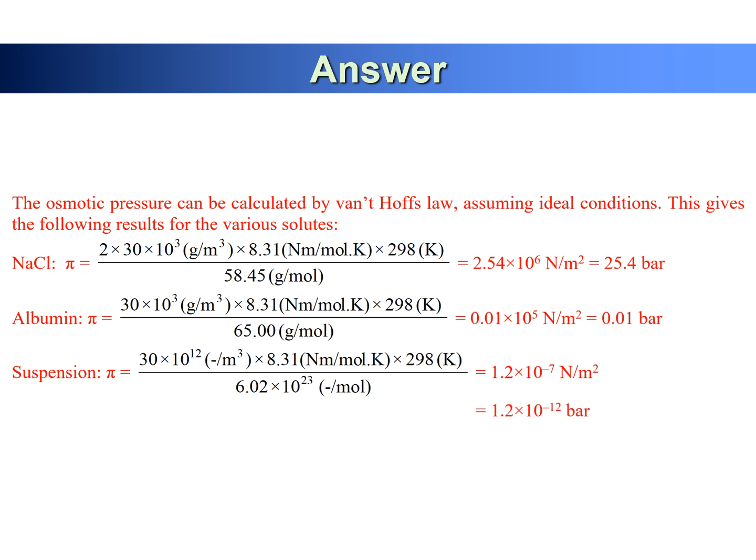In this case, we have two options. One is total dissolved solids. You can simply measure conductivity, which can be converted to total dissolved solids, and we can roughly calculate the concentration of your salt and then convert it to your osmotic pressure.